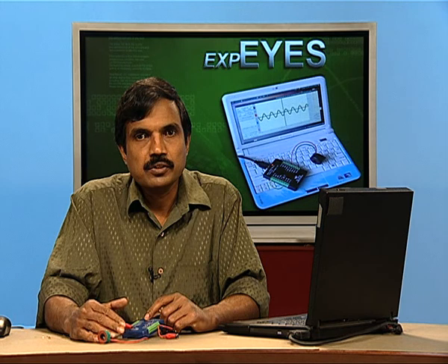So, now we have completed the measurements. We have seen the cases of RC, I mean resistance and capacitor alone, and resistance and inductor alone. In both cases we have the monotonous response of voltage across the capacitor, and then we tried the inductor and capacitor together and got the oscillatory response also. So, this concludes the transient response of the RLC circuit.